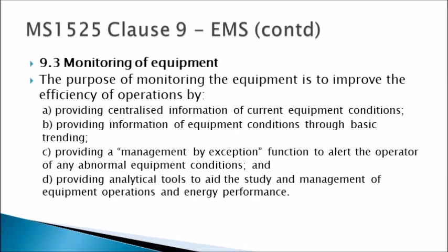Monitoring is an important part of having EMS. It's a very good, a very clear benefit. Then you have centralized information of equipment conditions and providing information of equipment conditions through basic trending. You can predict how equipment is being used throughout the year. Providing a management by exception function to alert the operator of any abnormal equipment conditions, and you can easily detect if any particular equipment in your building service is not functioning properly.